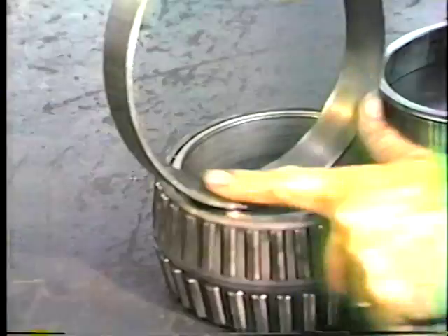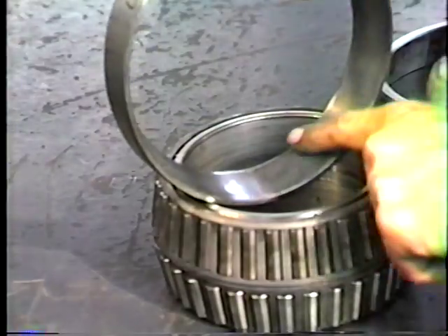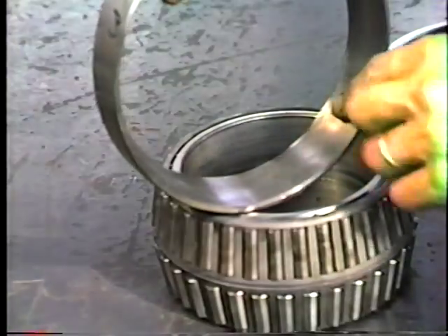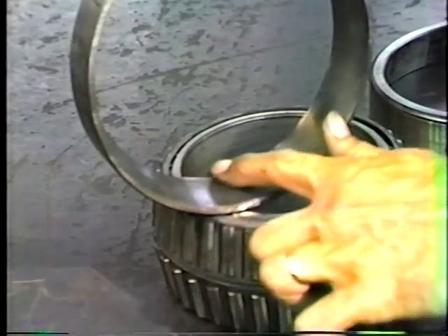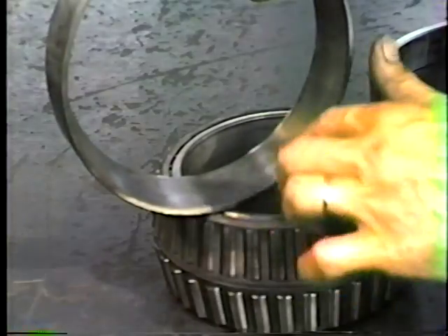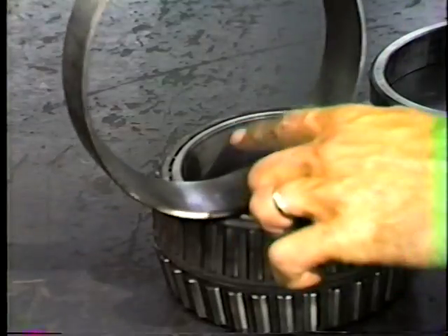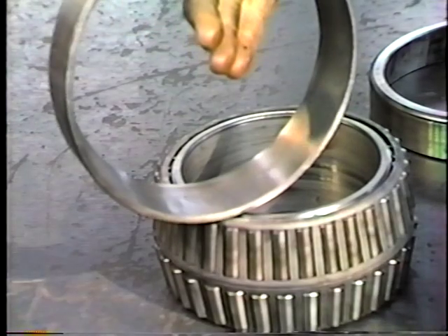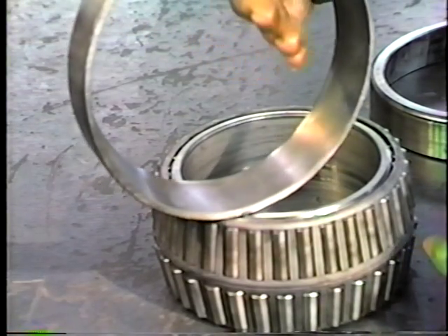There's no brinelling or any other signs of spalling or wear in there. It's just that the grooves, or the rolls themselves, are worn, that track in that bearing. In other words, obviously the bearing has worn by that amount, because those grooves are not in there when that bearing is put together. That's where the bearing wore. Okay.